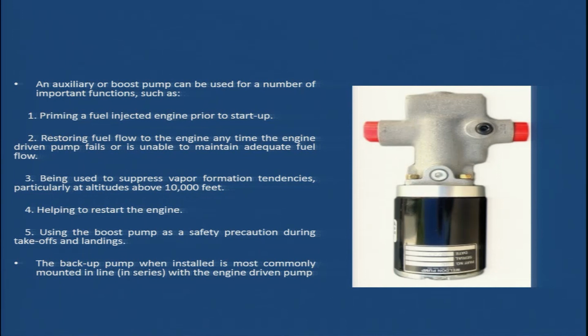Restoring fuel flow to the engine anytime the engine driven pump fails or is unable to maintain adequate fuel flow. So, in case the engine driven pump fails or is not able to maintain the required fuel flow, in that case also the electric fuel pump comes into picture and supplies fuel to the engine.